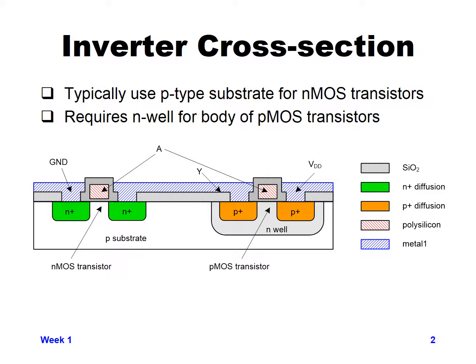Those two P+ regions for the source and drain will be formed, and then between those two regions, again, they'll deposit a gate oxide underneath a polysilicon gate. The polysilicon will be used as the gate material for the PMOS transistor. And so here you can see an NMOS transistor created and a PMOS transistor created inside of an N-well.